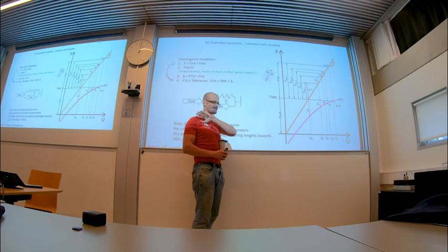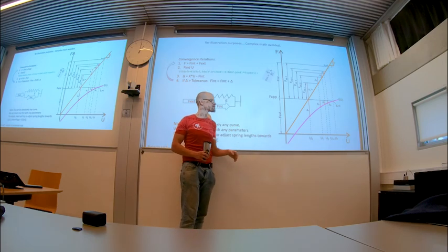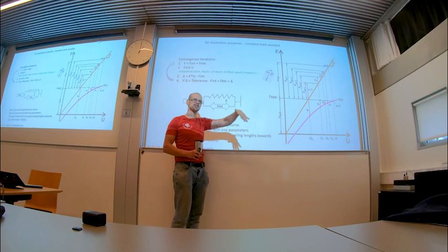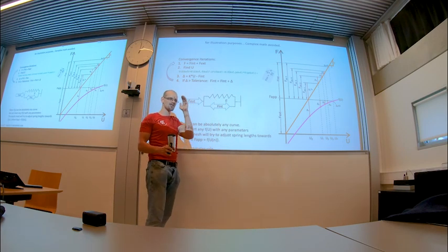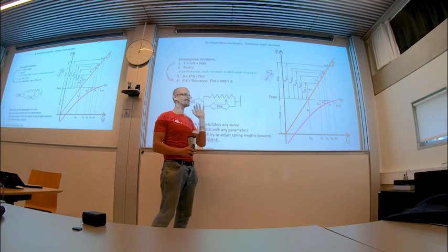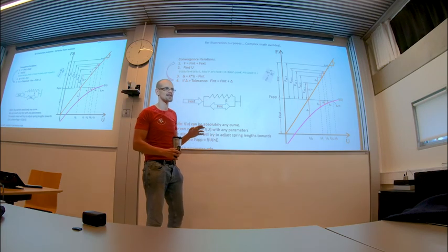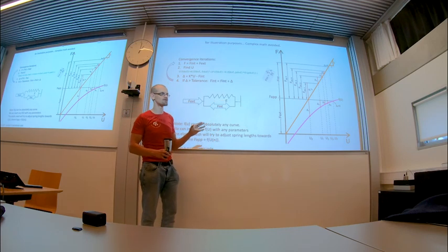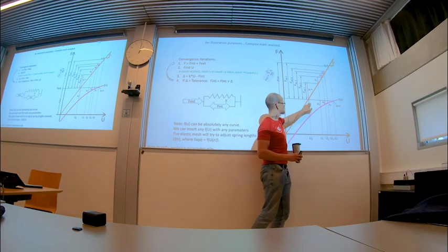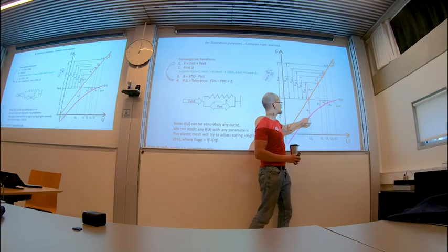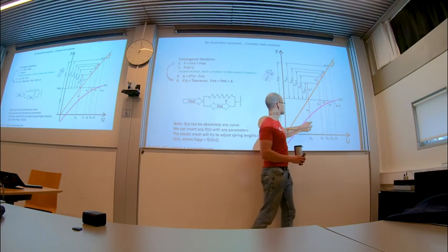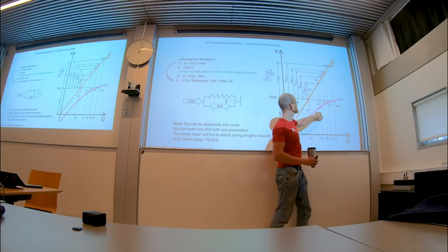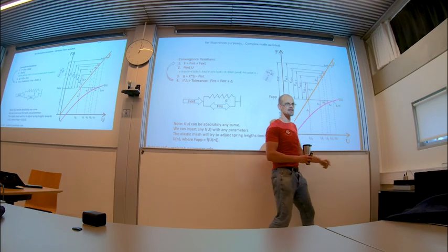And there's hundreds of different algorithms to do it. There's PID controllers, there's Runge-Kutta, and all kinds of derivatives of different degrees, adaptive slides. And then you have a million elements all trying to wiggle around into positions. You cannot put it in your head. You will have to run simulations of that. But be aware that this is what all iterative convergence solutions do. They make a guess using elastic. I want to be on this curve, so I'm this far from this curve at this displacement. Okay, let's add this here. Okay, I'm this far from the curve I want to be on. Let's add this here. That's a million times.